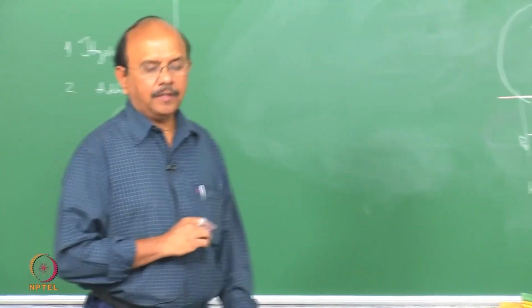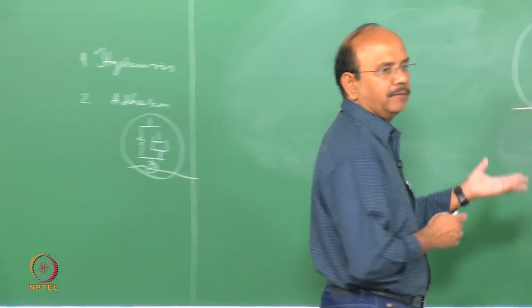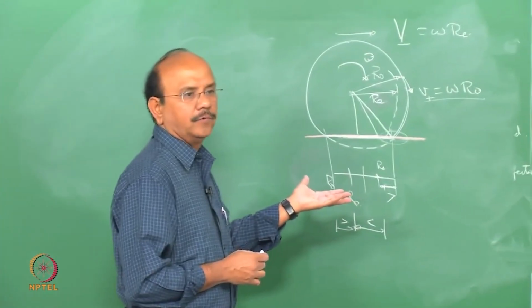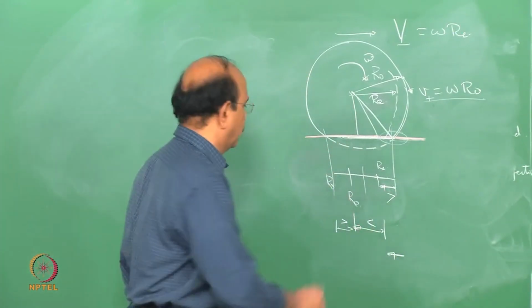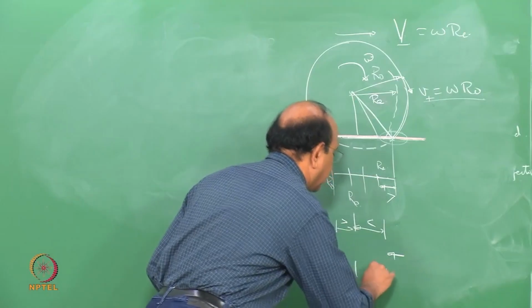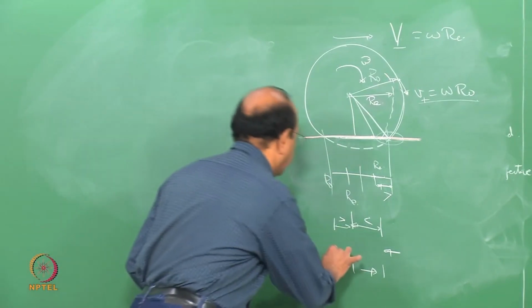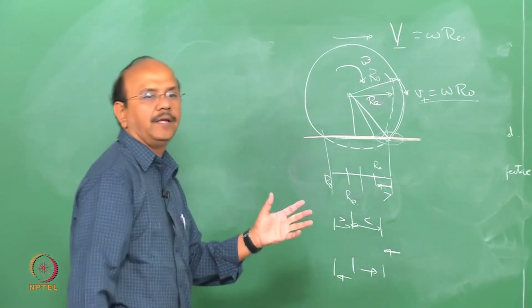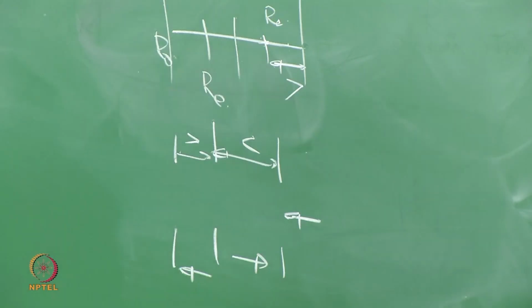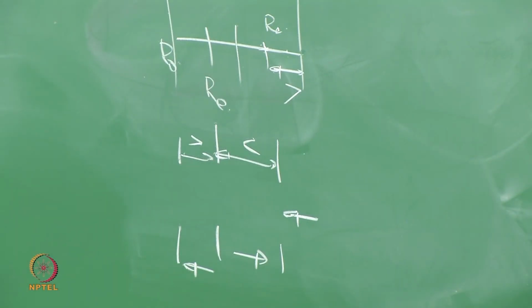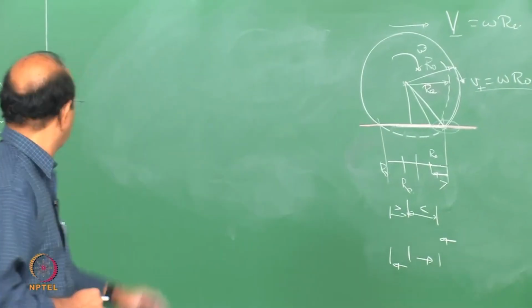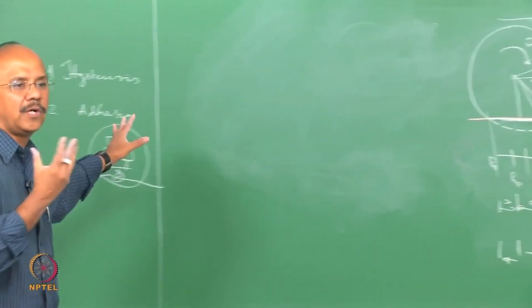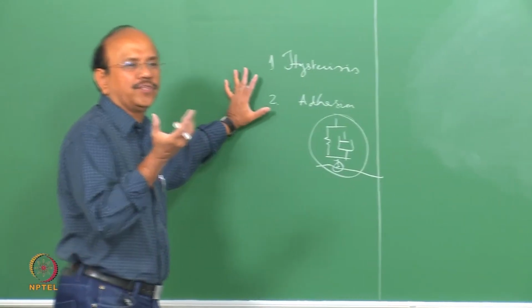So, if you look at the direction, you will see that they are in one direction up to this. From here to here, that will be in the other direction. From here to here, that will be in this direction, and it goes up. What are they? They are slip. An interesting point is that we just now saw that without slip, there is no friction.